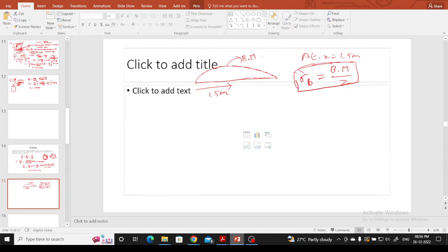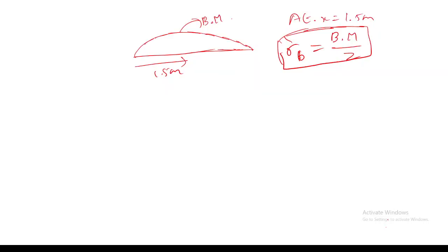I haven't read like that. Whereas you can find out the average shear stress value at a cross section, you can't find out average bending stress at a cross section, to my knowledge. Even if the bending stress is linearly varying, since it's varying, I don't think we can come up with some kind of average bending stress value.